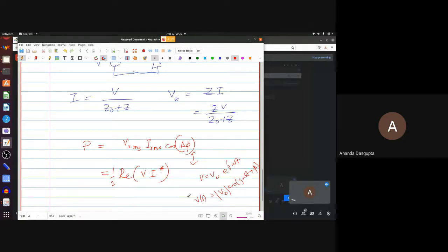There is a real part of the voltage given. What you actually use in practice, at least when you specify your voltage and currents using 25 angle 0 degree or whatever, some magnitude angle convention, remember what you are specifying is actually the RMS value. So your actual V of t will be root 2 times that. So there's an extra root 2 in V, extra root 2 in I. And that actually gets rid of the half. So if you're using RMS values for voltages and currents to give the magnitude and phase, which is the convention anyway, there will be no extra half.